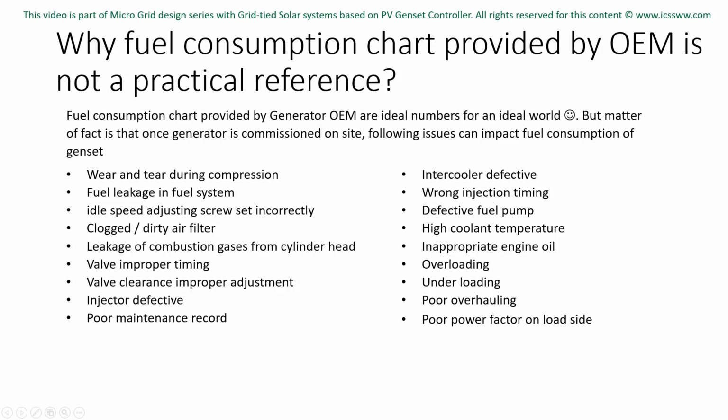Number 10, wrong injection timing. Number 11, defective fuel pump. Number 12, high coolant temperature. Number 13, inappropriate engine oil. Number 14, overloading. Number 15, underloading. Number 16, poor overhauling. Number 17, poor maintenance record. Number 18, poor power factor on the load side.